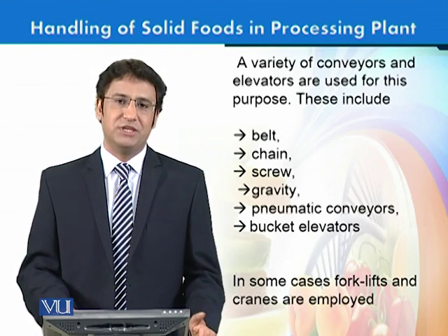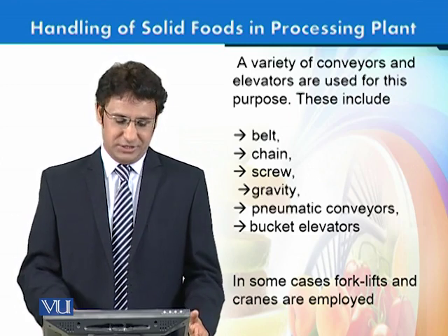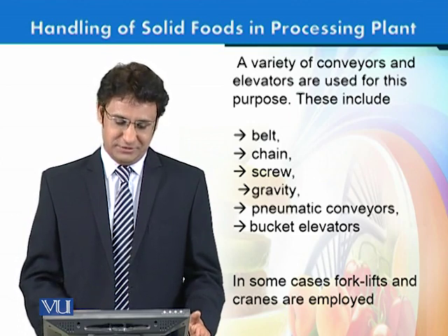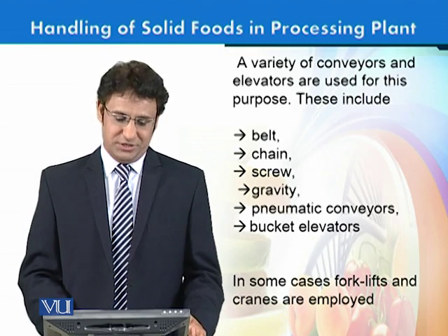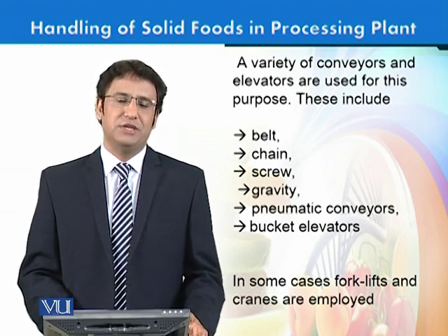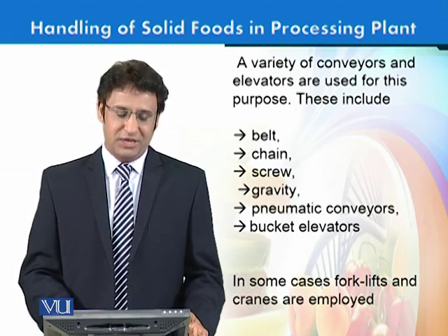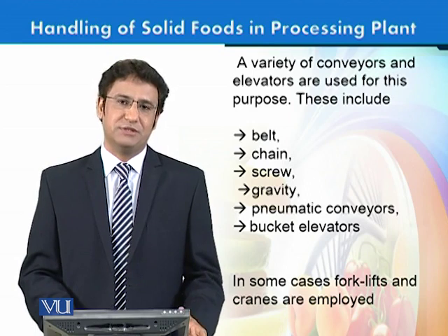Gravity is one factor, where the pull of gravity is utilized for movement of solid materials. We can also use suction pressures, which is called pneumatic conveyors, and an old-fashioned system, bucket elevators, for the transfer of materials vertically.